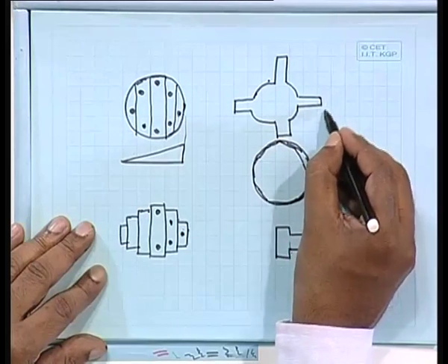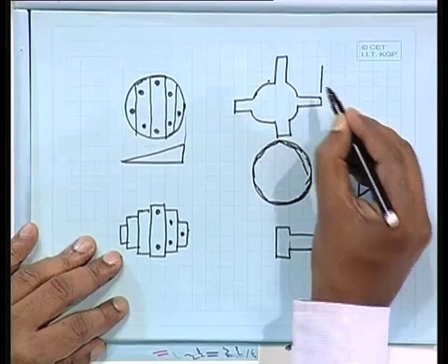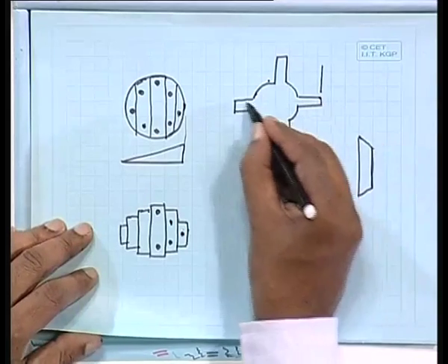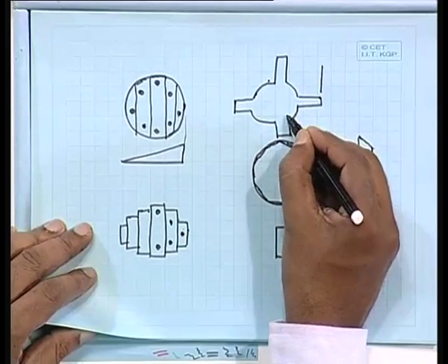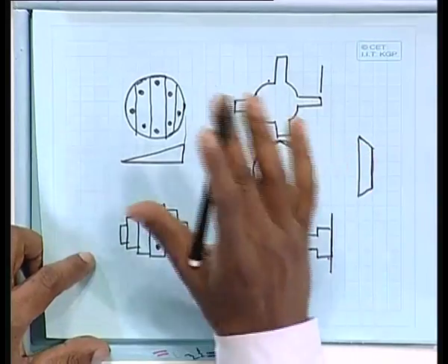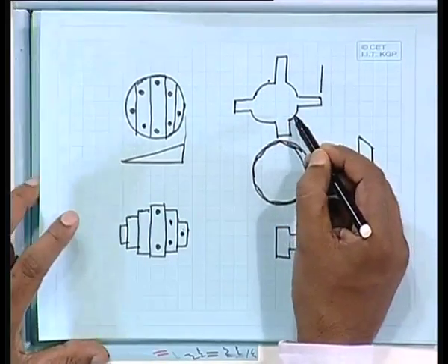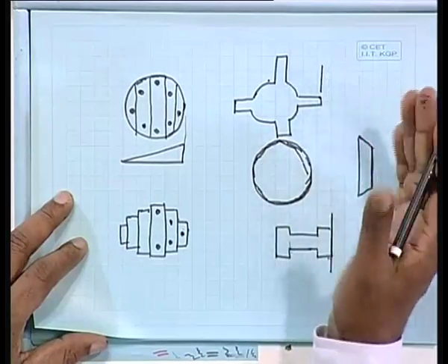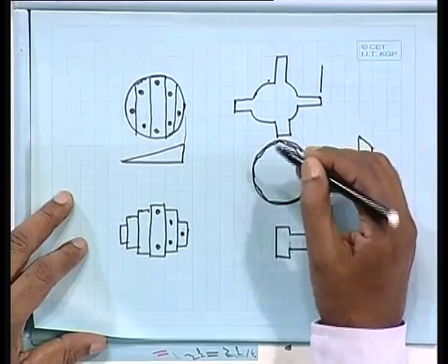What you have to do, again, you have to find out the same strain diagram as if you are having this with the maximum stress. So, I can find out what is the maximum stress and this is the minimum stress, and I can find out again the interaction diagram for this curve. In fact, when I got this type of industrial problem, I thought, okay, let me do my own, because nowhere can I do anything using, say, SP16. So, I have to make my own.